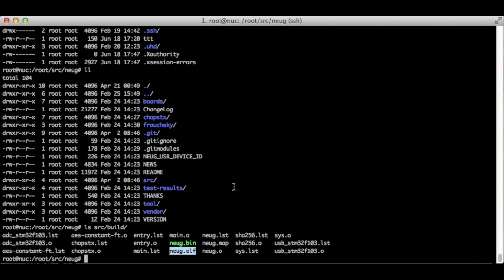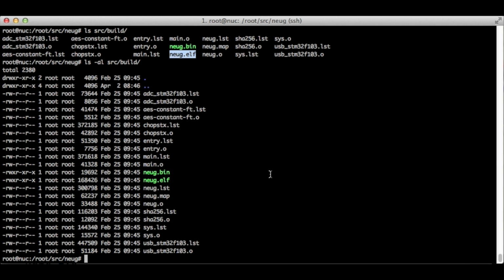We have to delete whatever is on there. You have to unlock it, delete whatever is on there, and then flash that file to the device. Let's get an idea of how big this is. So it's a relatively small file that you have to push on there, but it is not easy because you have to get a device to talk to the thing. You can't program it through USB. You have to program it through placing wires on it.